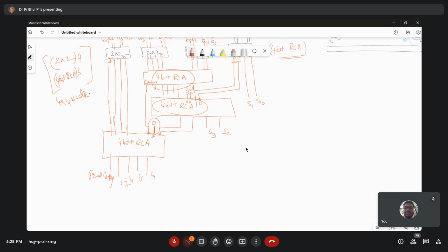Maybe if I ask you to write a code in behavioral style for this 4-bit, what is the size of your code? You have to define plenty of inputs, no? Combinations of inputs you need to define. That means comparatively for Vedic multiplication, structural style will be very simple. Component-wise, only 2 components you are taking. And for 3-bit Vedic multiplication, it is XOR, something like half adder, full adder, and an AND gate operation. So attempt using a structural style for Vedic multiplication in your lab.